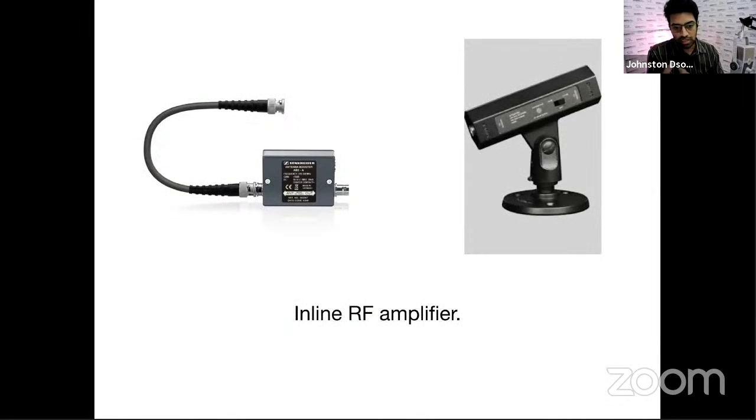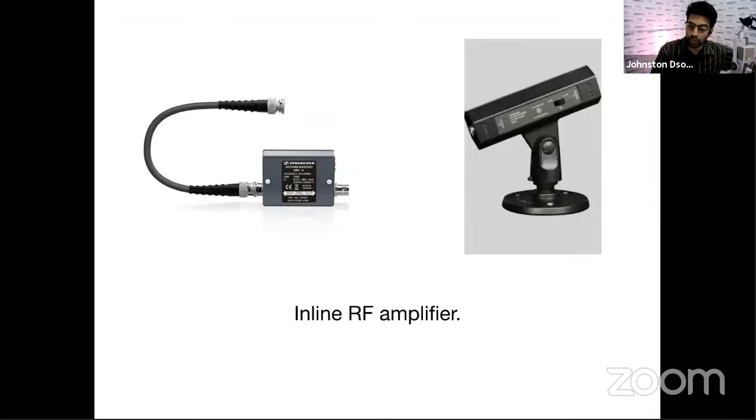These little things that you see on your screen are basically amplifiers. So if at all you have to run very large cable runs, there's a way of measuring the level, the signal drop. So if the signal drop goes beyond 5 dB, you need to basically have an inline amplifier. So you'll take your RF output, connect it to the input of the amplifier, and the output of the amplifier will give you an amplified signal. Now this amplification is not audio amplification. This is RF power amplification.